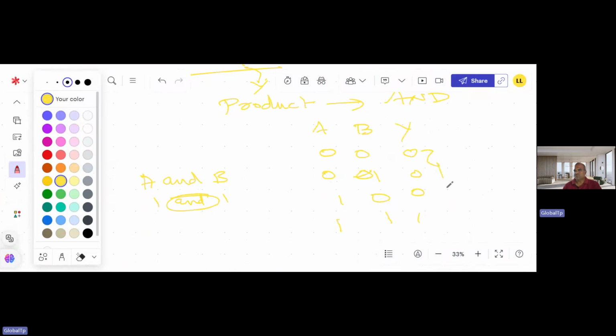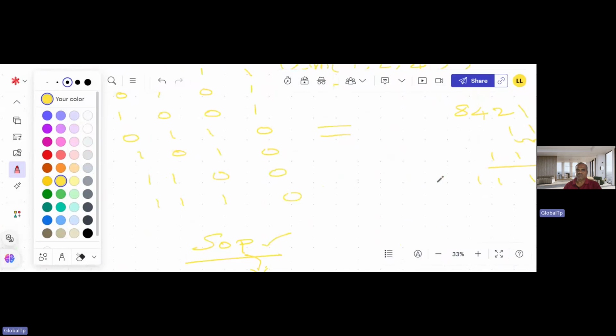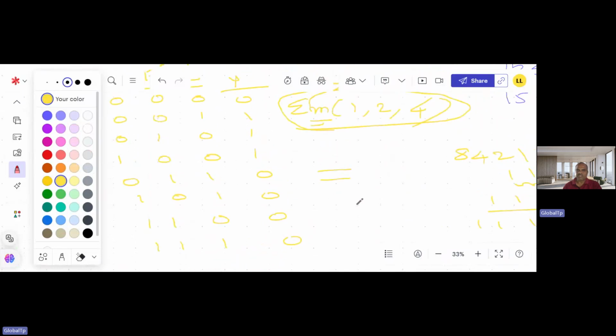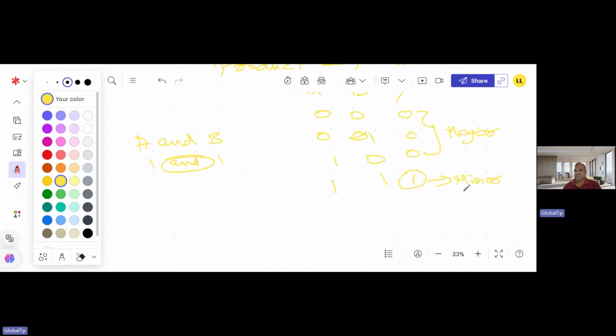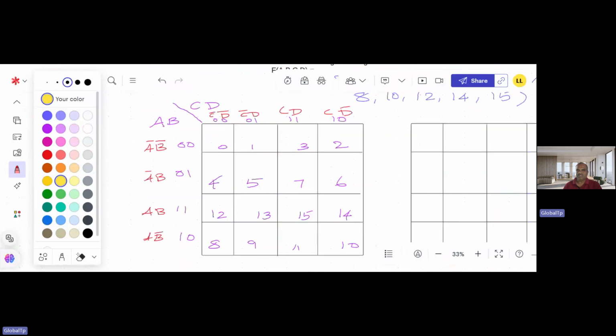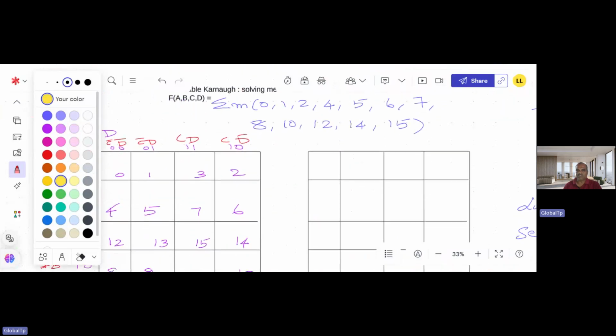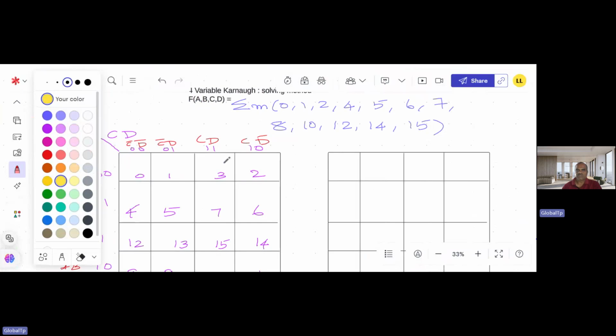So when you visualize here, the 0s are major in number and the 1s are minor in number. The 1s are going to contribute to the equation. Whenever the output is 1, the circuit will be functioning; in all the remaining cases the circuit will be off. So here all zeros are omitted and only my high condition will be functional. That is why we call it minterm, and that is why this circuit is sum of product.